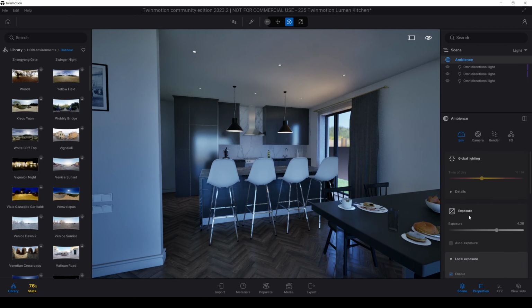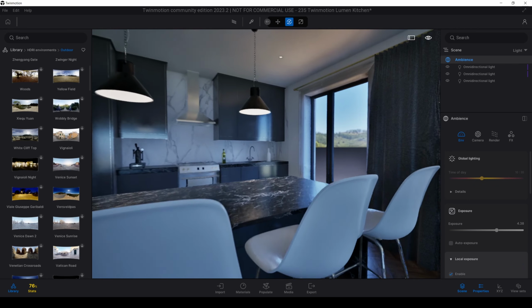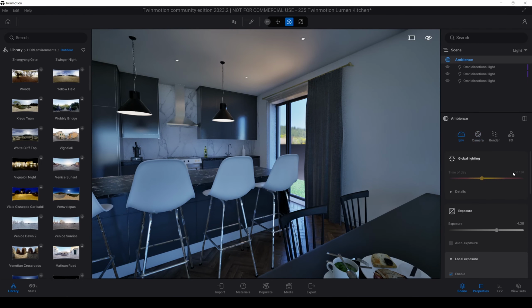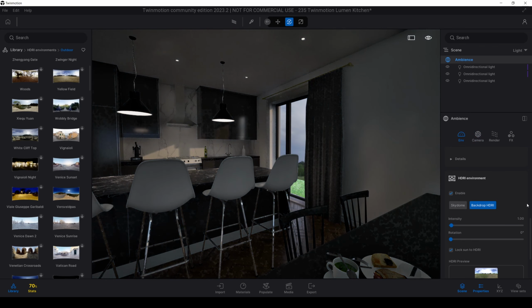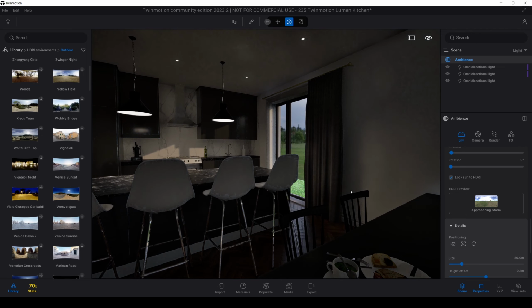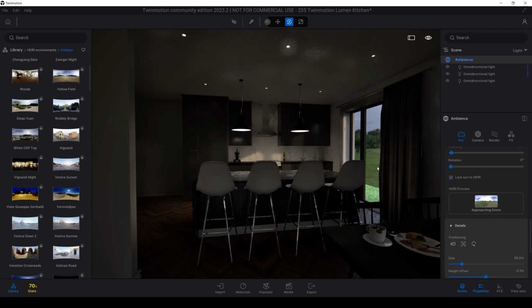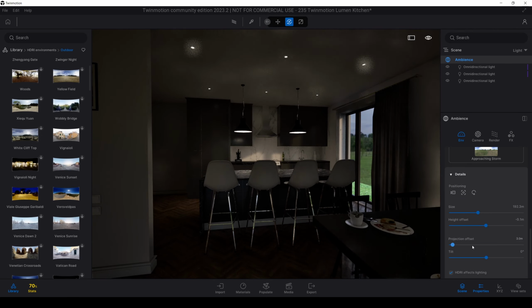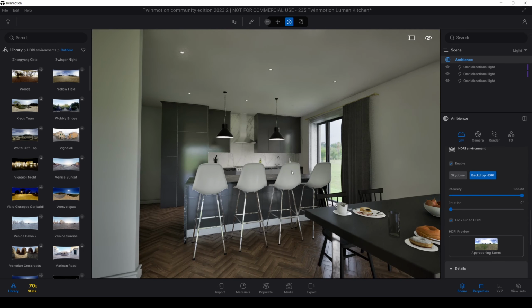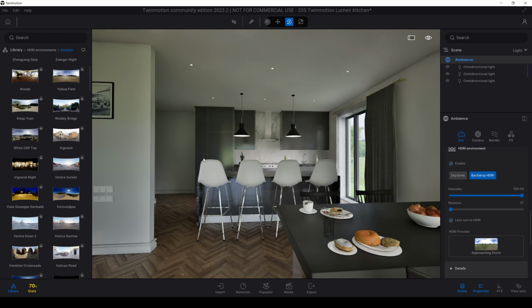Okay, well enough, but it's too blue. To make a realistic render, we must make it white. By the way, if you want to see this dark place in your render, you can switch to Backdrop HDRI, and from here, click Details, click the Center Backdrop, and you will see the terrain. Actually, since we have more green in the background, our scene turns to green.